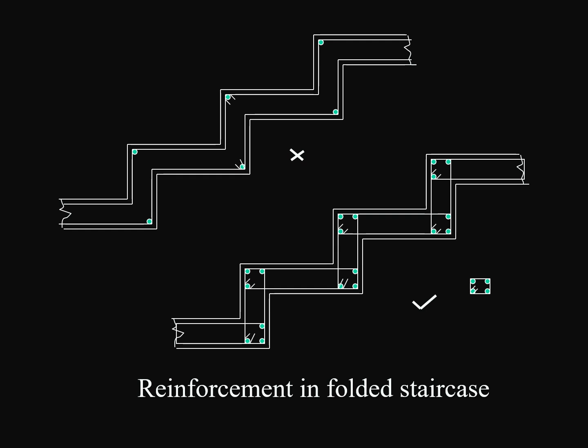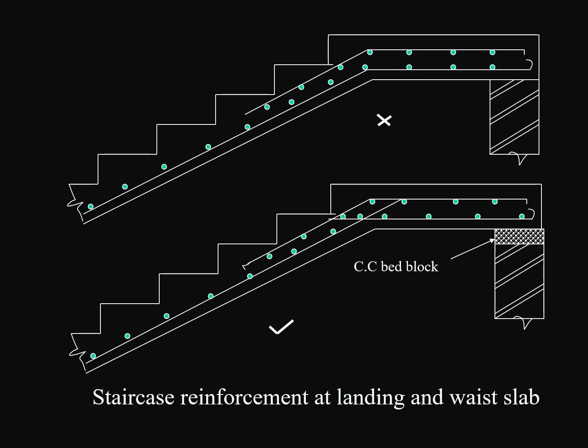But for every corner I have shown 3 bars, but generally another bar will be provided which is like a small lintel structure. Technically speaking, the 4th bar which is not shown is not required. However, for the ease of construction, they provide a lintel structure at every corner as shown here. You can see the reinforcement shown for staircase.